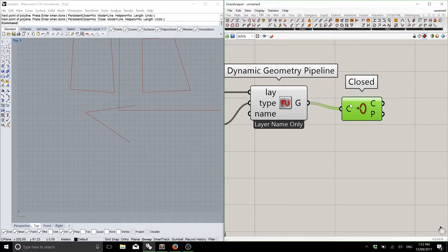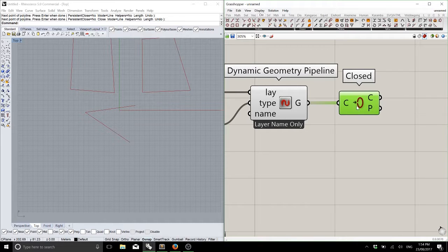Tell them how to, when they type and they don't know where to find it, the reverse way to discover words. You mean like this? That way? So if I've given you a script or you've downloaded a script, or let's say last week you put something in, and seeing as all of you have completely forgotten what the matrix thing that I said last week, you can hold Control Alt, and if you hold down on the component, it will show you exactly where you can find it in the ribbon.